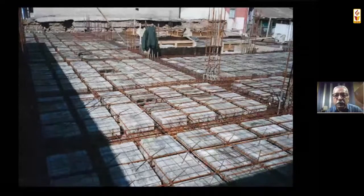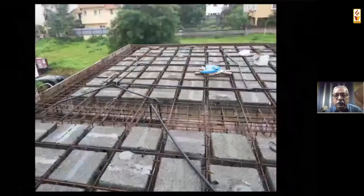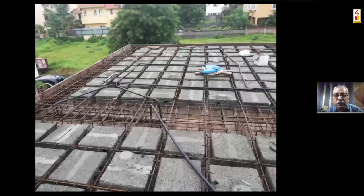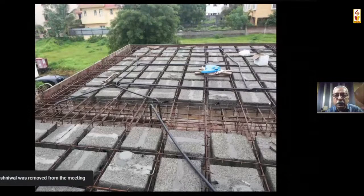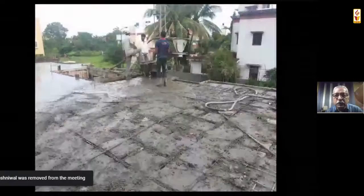So here you can see those concrete columns are there. And this is like load bearing slab, where columns are not visible. And then you can do, of course, the electrical part on top, and then you have to lay 4 inch by 4 inch, that is 100 by 100, 14 gauge weld mesh on top of it to reduce the hair crack, because the upper layer is just 50 mm thick.